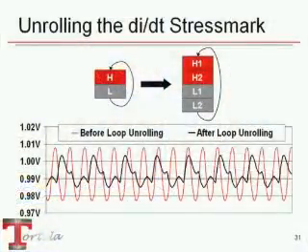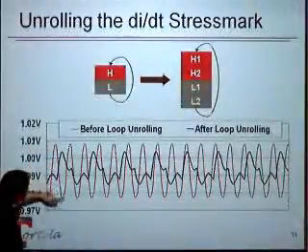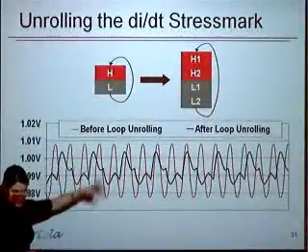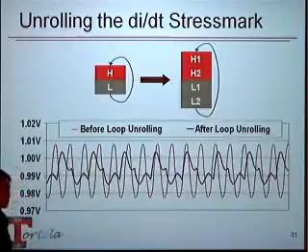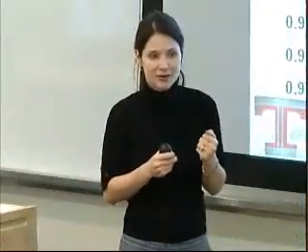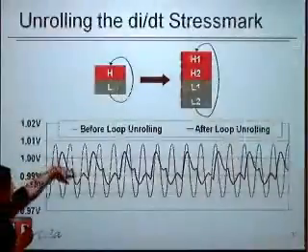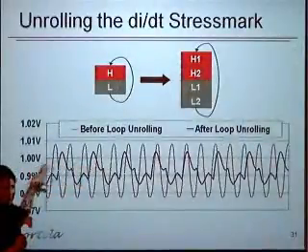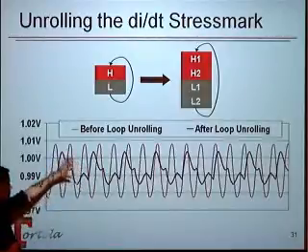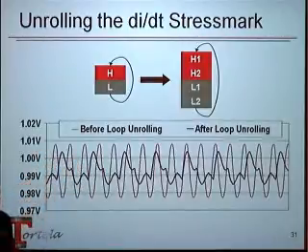Okay. Right. So for this particular example, we took the power virus. What ended up happening is we took that power virus, and here's the before case where it was doing exactly what it was designed to do, which was this fluctuation. And then what we did was apply loop unrolling to that particular loop, weave together the high power, low power sections, and that's where we were able to slightly smooth out the problem here. So if you envision this, where you have some hardware mechanism to say, hey, I'm having a problem, software mechanism comes in and fixes the problem. That's really the best of all worlds.